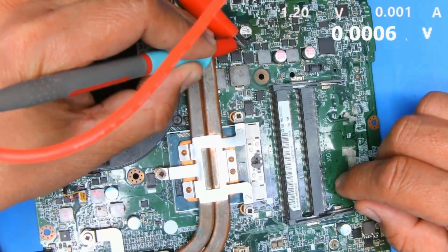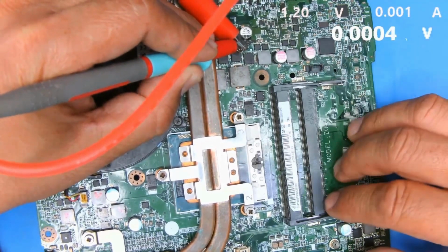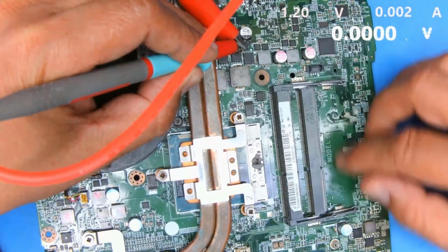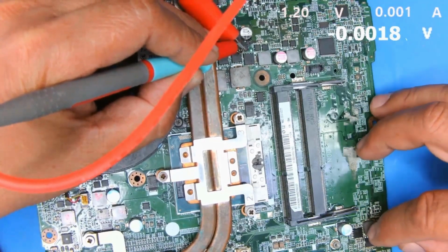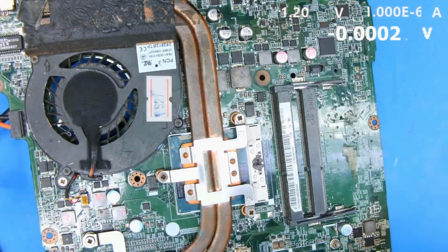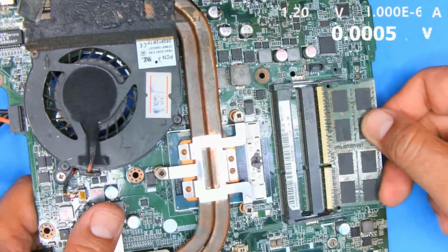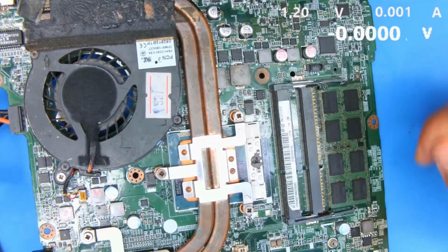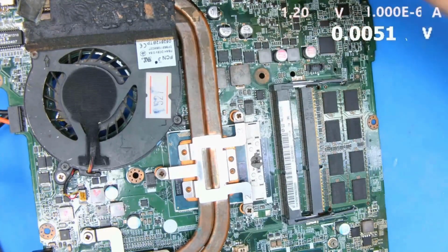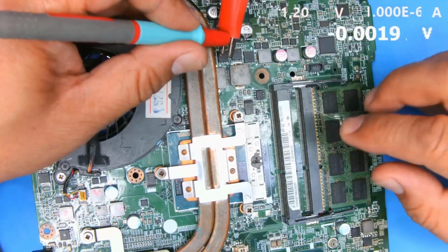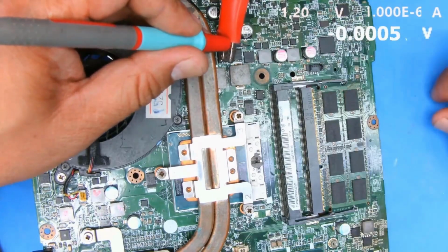Just about 0.02 amps. There needs to be a load for it, which means the power must go into a load as well. The load I'm talking about is the RAM at this point. This is the point where power is supplied close to the RAM, so we need to install the RAM as well. See, there's a risk, because if you put a load in, there's a chance that all the power will flow into the load. But this RAM is DDR3 RAM, it uses 1.5 volts. So if we set it to just about 1.2 volts, it won't break. Supplying power to the load like this won't damage it.